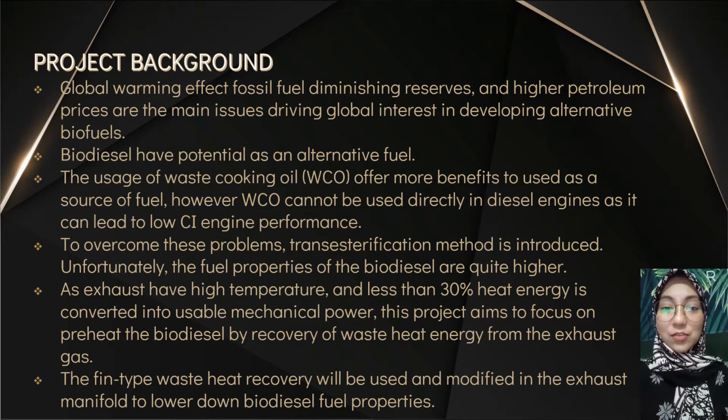Unfortunately, even after biodiesel goes through the transesterification method, the fuel properties of biodiesel such as density and viscosity are quite higher than conventional diesel fuel, which can decrease CI engine performance.